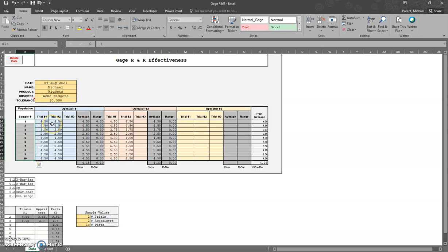If you know how to conduct a measurement system analysis, this will look very similar to you, where you're measuring the same thing several times in these different trials. You can see here that in all of these cases, except one, this operator agrees with him or herself. And over here you see that there is a general agreement and it doesn't look like they've missed anything. We've got the average, we've got the range, and you can see that the range is 0, which is to say that there were no differences in the measurement between trial 1 and trial 2 of the operator.